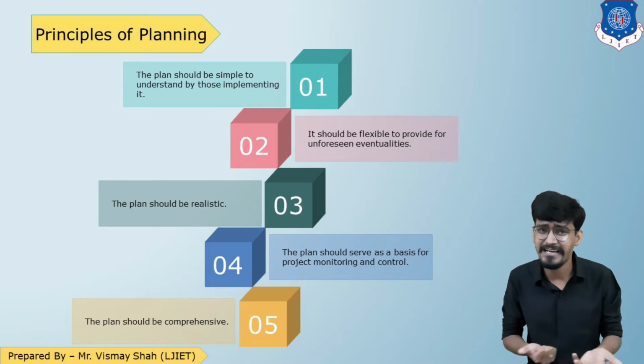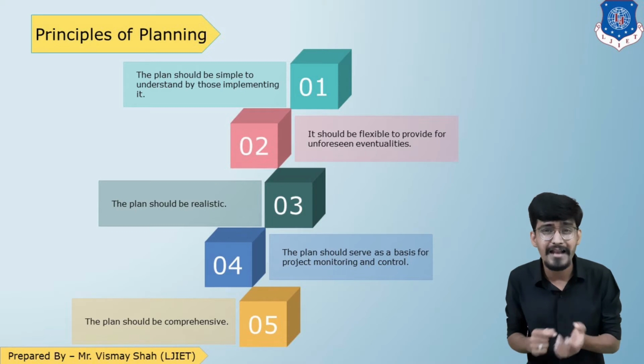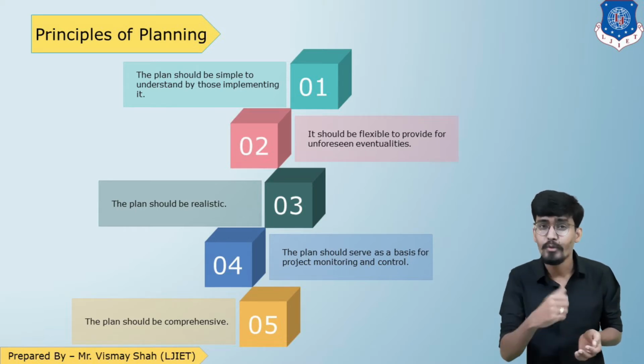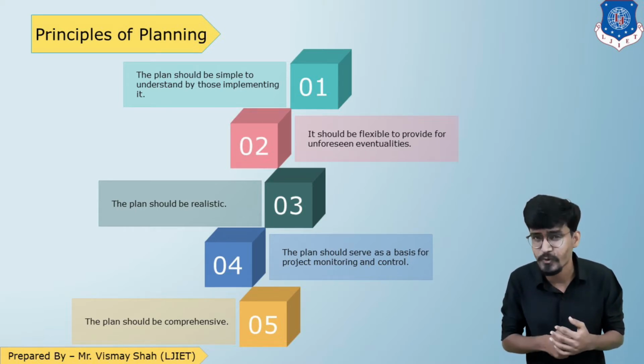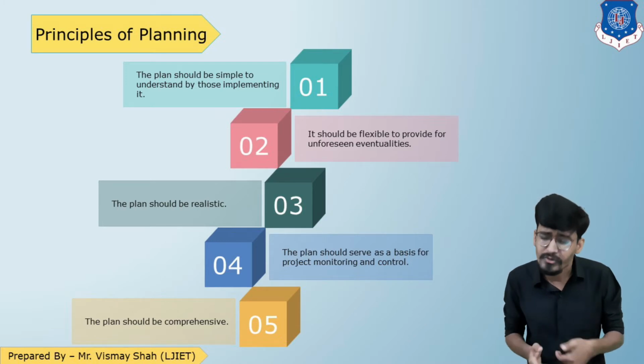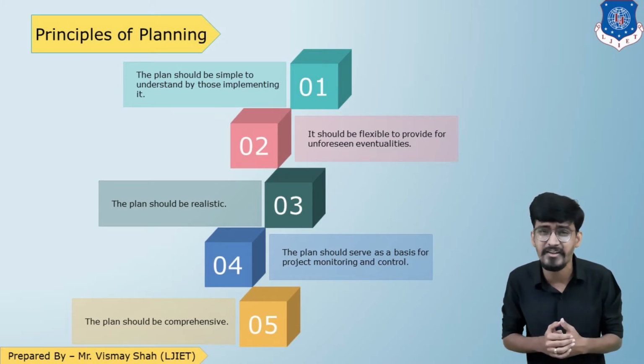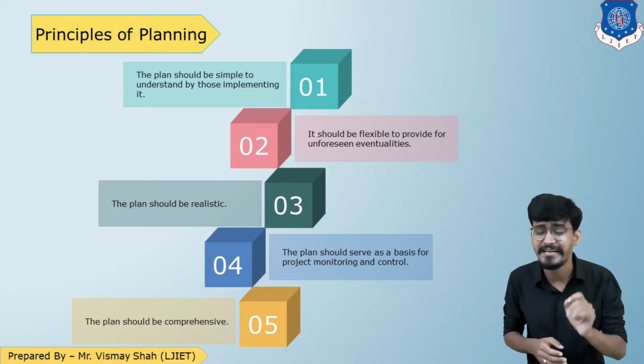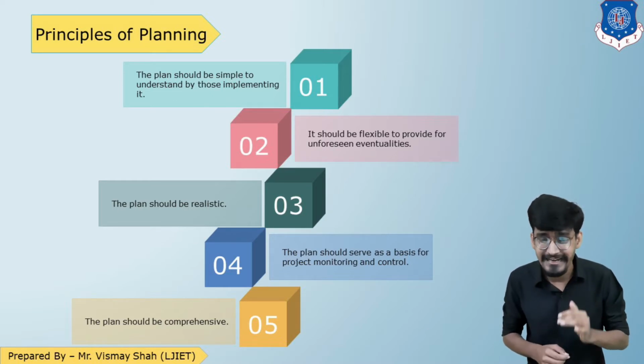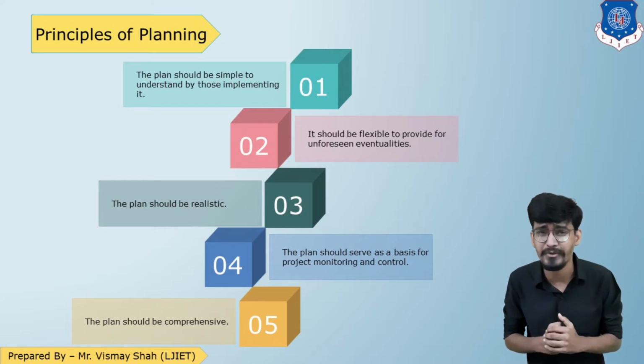And the next principle is your planning should be realistic. You don't plan just for things on paper. Like, your boss has told you to complete this project in 300 days. On paper you can prove that the project can get completed in 300 days, but you have to consider the site criteria: is it really going to complete in 300 days, or does it require 320 days or 325 days? So the plan should be realistic.